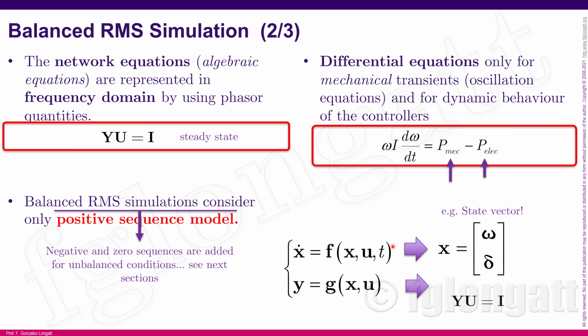What I'm trying to tell you is that in practical terms, from the mathematical point of view, the differential equations will define this set of differential equations here. And for instance, representing the network, we can use the admittance matrix, and we will consider this set of equations for the nonlinear algebraic equations, okay? And that is very simple. Okay, but this is the mathematical representation for the differential and algebraic equations, equations related with the dynamics, for instance, coming from the synchronous machine, but also algebraic equations coming from the network.